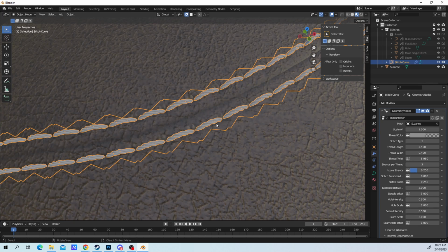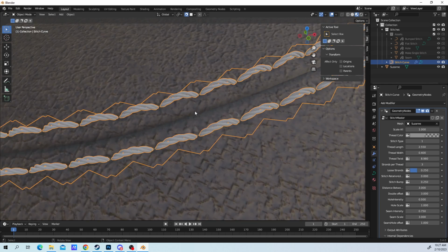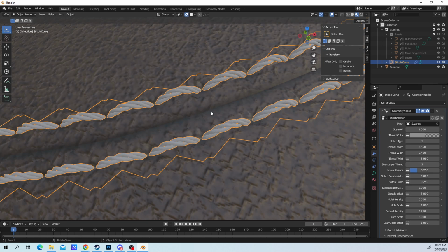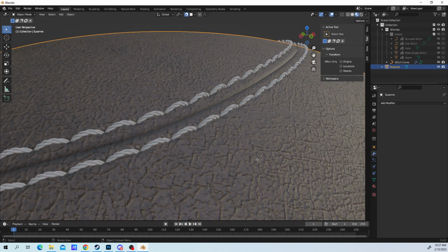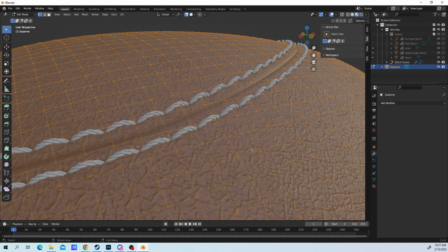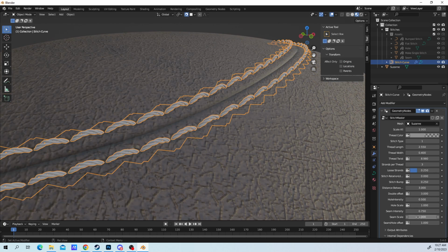The last one is for some extra troubleshooting if you do run into issues. If these here are starting to clip the surface that you're working on, either your geometry needs to be smoother so that you have a better surface to work with, or you can adjust this scaler to pull the shadows and the seams out from the surface a little bit more.